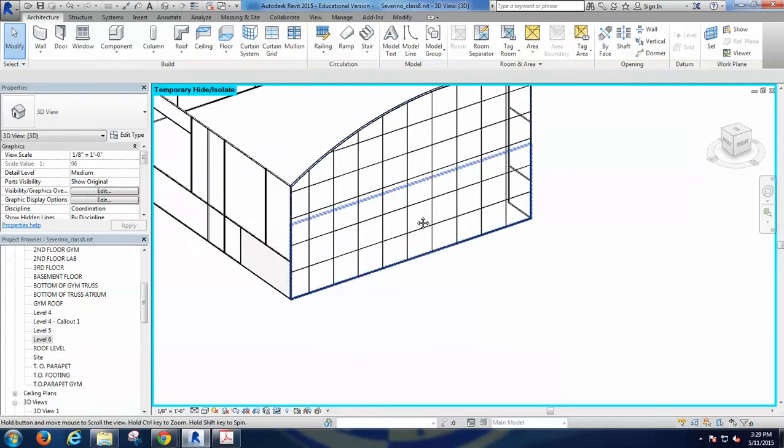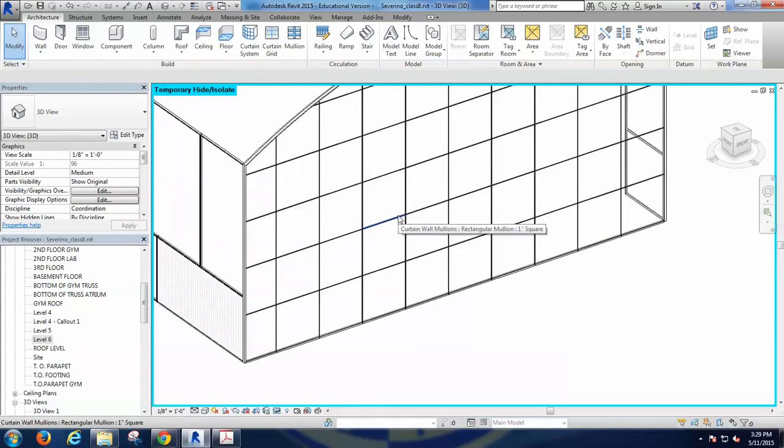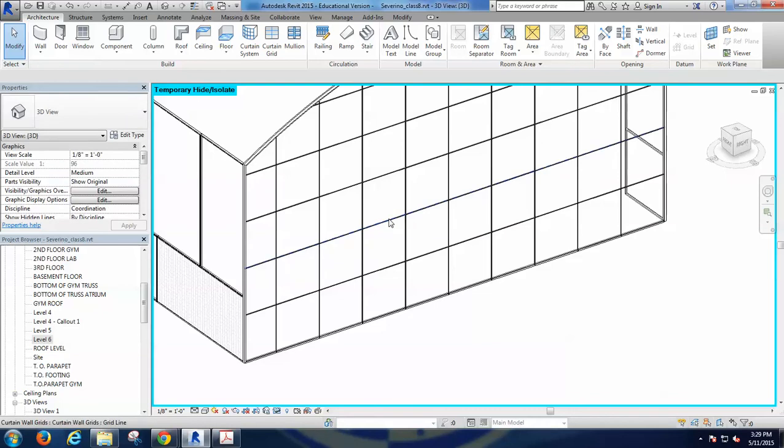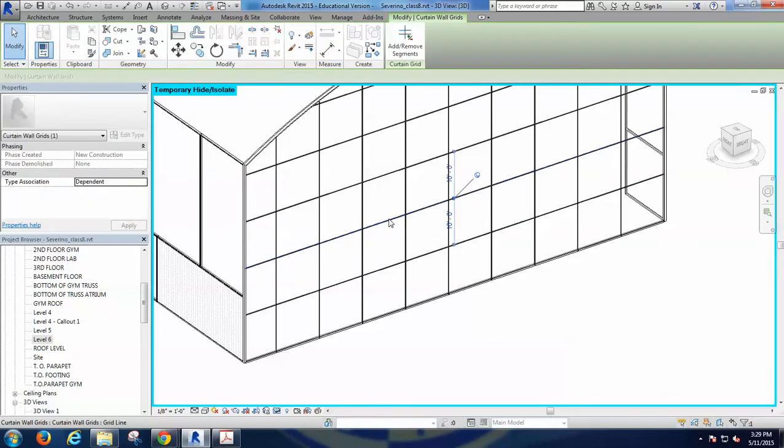Good. Can I change the grids where they are? If you tap on top of a mullion, which is the first thing that you normally locate, you can tap and select the grid line, and as we did a long time ago, you can uncheck the linking option and move it freely.